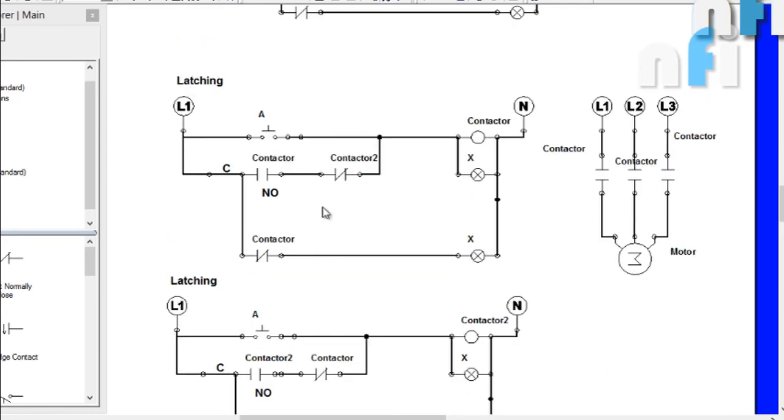Okay. So how to change the direction? This is called changing the direction of motor using a single circuit, I mean using 2 push buttons. If one is pressed, it will be forward. If another is pressed, it is reversed. So how to go for that? How to do that? So I'm going to rename the circuit as AC motor direction control.